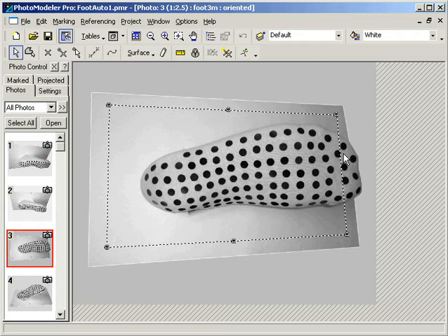In this project, we have used control points seen here along the rectangular base to orient the project. You can mark and reference regular non-control 3D points across the photos to orient them if you are able to find enough points. In addition to these point requirements, there is the requirement that sufficient good quality photographs be taken.